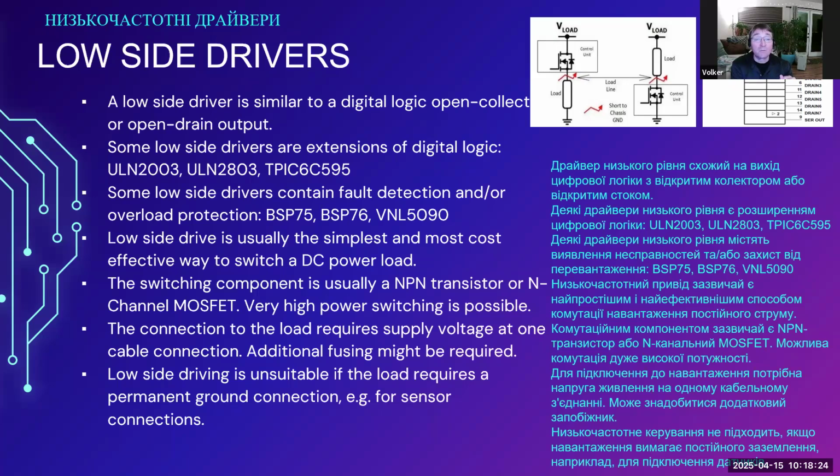Okay, low side driver, essentially, this is the equivalent of an open collector or an open drain output in the digital logic that I had mentioned earlier. So a low side driver switches the load to ground.